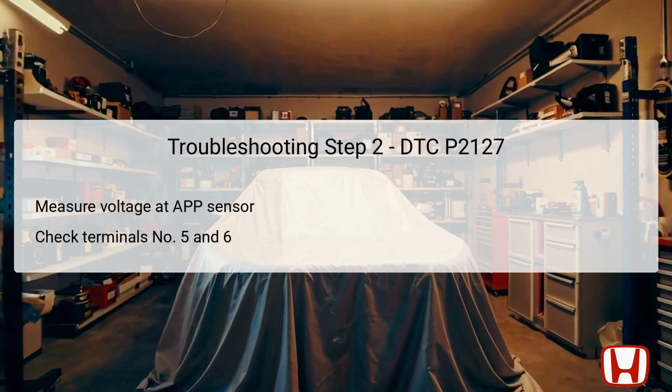Conversely, if there is no voltage at this level, this signals that there could be an extensive issue, which would lead to the need for more detailed diagnostics to be carried out, particularly looking into potential wiring issues or supply voltage problems. This step begins with the technician turning the ignition switch back to the lock position to ensure that the system is off and safe for further work.